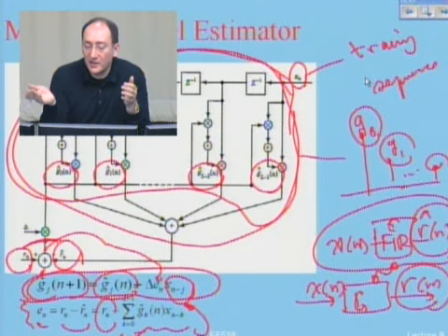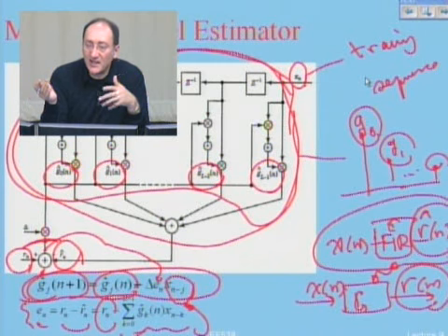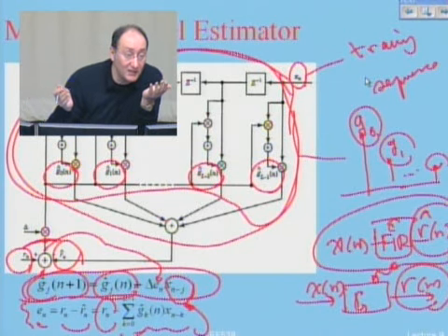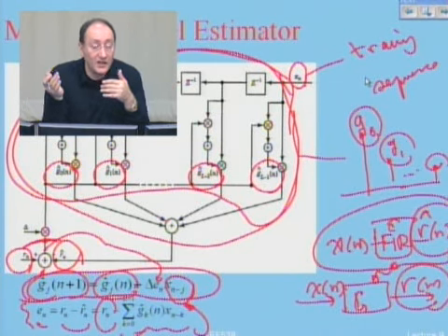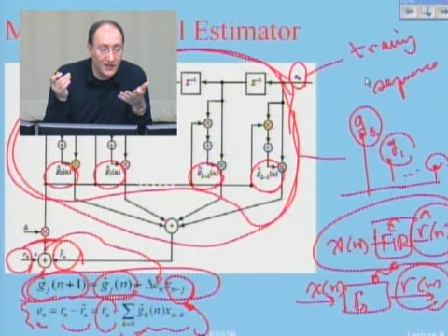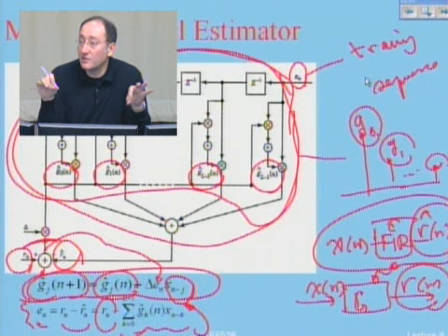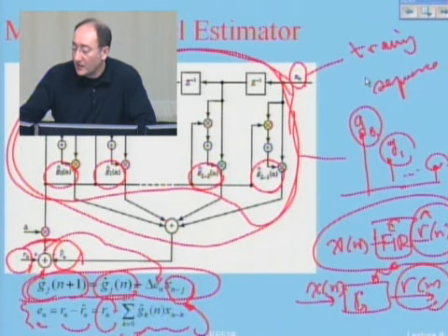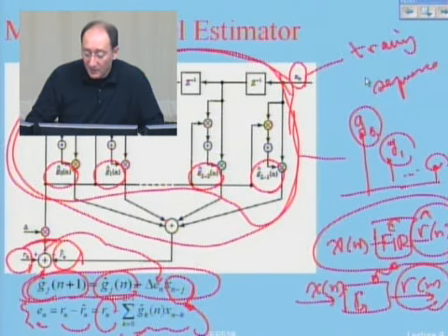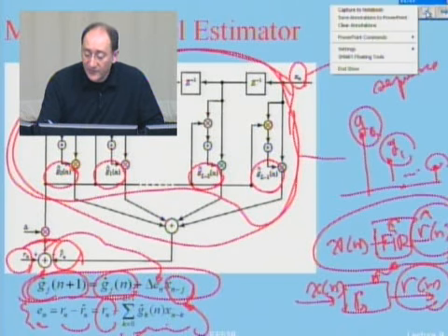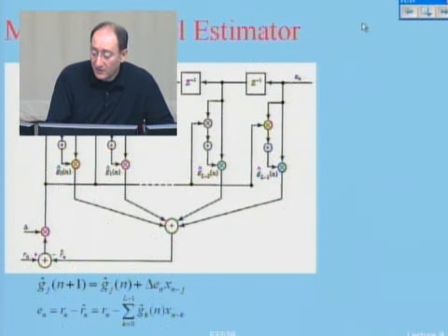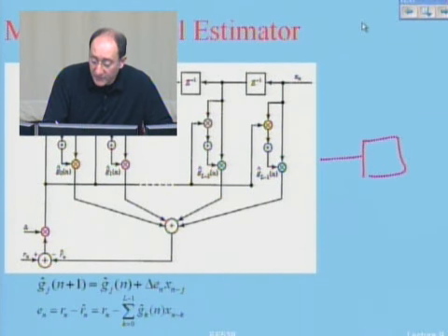At the receiver, I'm sampling at a rate of something like 4 times the bandwidth, for example, so I have 4 samples per transmitted pulse. And I can measure that impulse response. And if I measure it, in summary, my system is represented by a filter called G, for example.